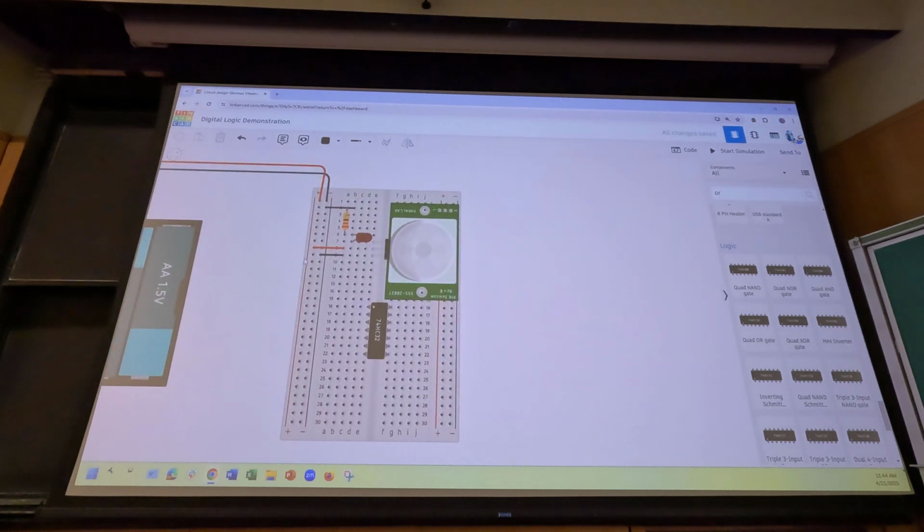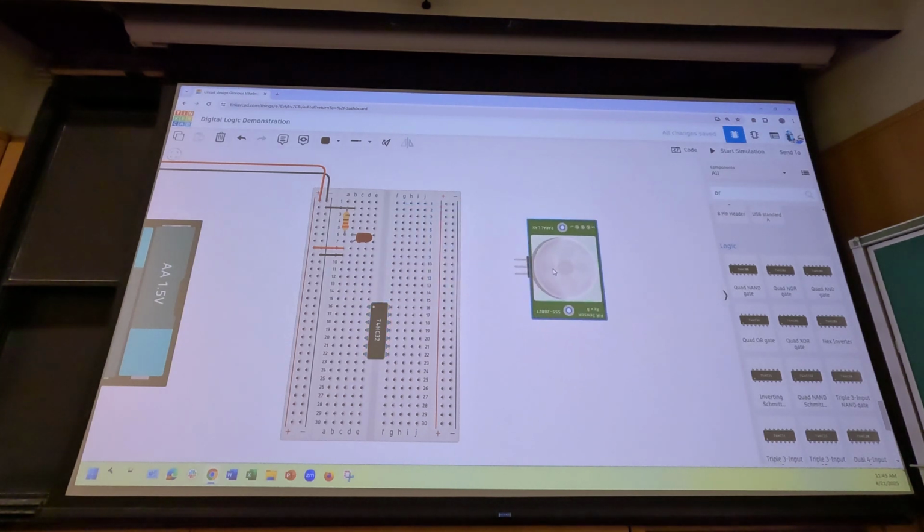Okay, now what I want you to do, rather than me doing this for you, is wire this so there are 4 sensors, and any one of them detecting motion will cause the LED to turn on. Again, think of this like an alarm system, right? You don't care which sensor went off. You just want to set off the alarm if any of the sensors detect motion. Okay, so you've got at least, well, you can add more of these if you need them, but you've got an OR gate integrated circuit that actually has 4 individual OR gates in it, right? And you can add more sensors. Ultimately, I want this LED to turn on if any of the sensors detect motion. Okay? This doesn't actually require an Arduino. You're just doing it with hardware.